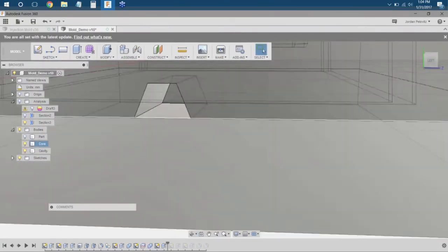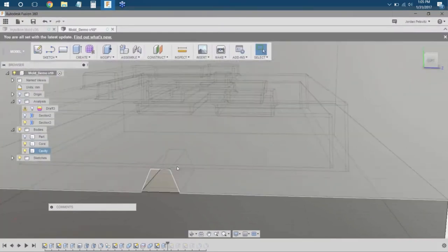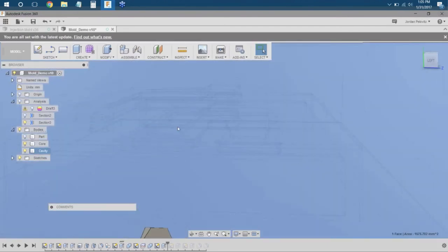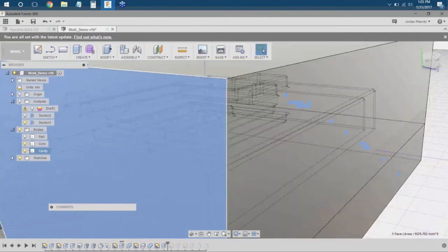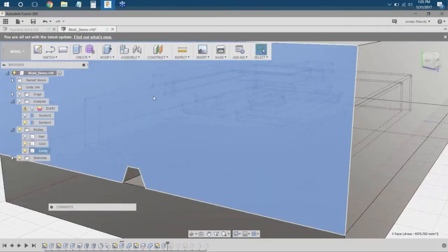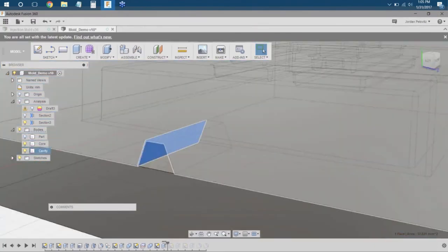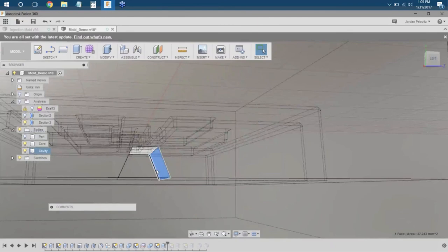In general, you want to have your injection port on both sides of the mold. The reason for that is if I added an injection port all the way up here, there's no way for me to remove that little sprue once the part comes out of the plastic because it would be completely embedded. It would be an undercut. So by adding this trapezoid down here, I've allowed it to be removable.